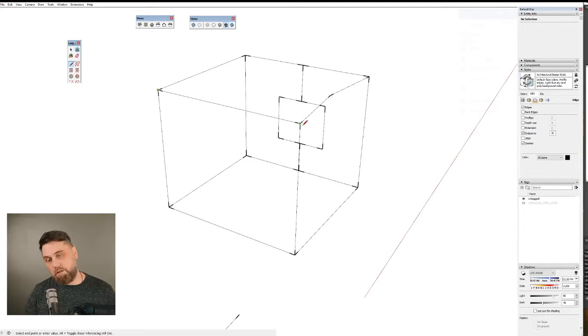So if we think about it in terms of framing, we can't put drywall on unless we've framed out a complete circuit in order to screw the drywall in all the way around, right? So it's the similar thing. You need to have your framing in order to screw in your drywall, right? The drywall becomes now the face that you're going to either apply a paint to, you're going to apply a wallpaper to, you're going to apply a stucco, a brick, anything, right? So you do your framing first, and then you come and hang your sheetrock or your drywall or whatever you're putting up, right? Your hardy board.